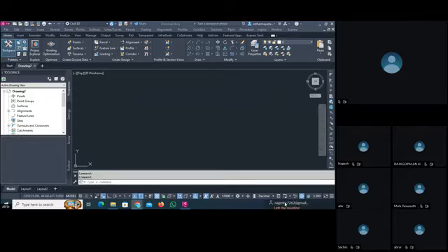In the last session, we learned how to create a surface, import the data, and prepare our base model. Today, we are moving into the core of highway design, where we actually start designing the road. Our focus will be alignment tools, profile creation, assembly creation, and corridor modeling. I'll give you a short introduction to baselines and regions, and then we shift to the cross section views. Today is very important because this is where the design starts becoming visible.